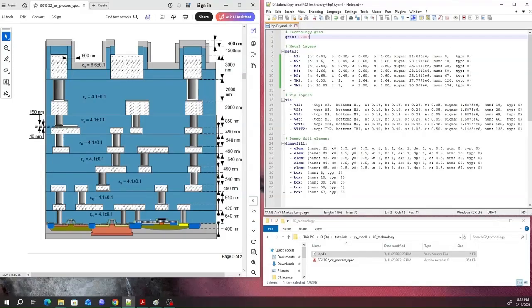For example, here, this is the metal 1. We have here name metal 1. Height is the height of the metal 1 layer, which is the distance between substrate and metal 1 layer. Actually, this reference point can be also backplate of the wafer, and that reference point is not that important.